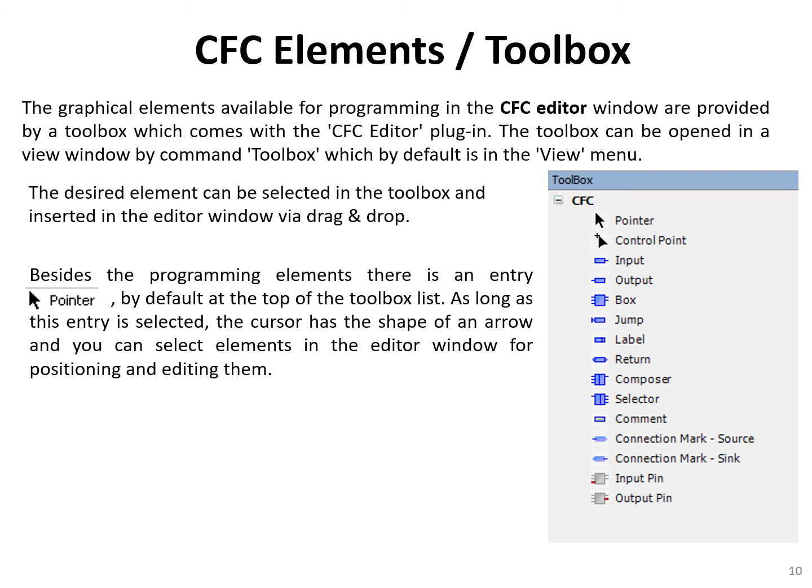Now we move to the CFC elements toolbox. The graphical elements available for programming in the CFC editor window are provided by a toolbox. This one, which comes with the CFC editor plugin. So once you choose the CFC programming language, you will see this toolbox. The toolbox can be opened in a view window by the command toolbox, which by default is in the view menu.